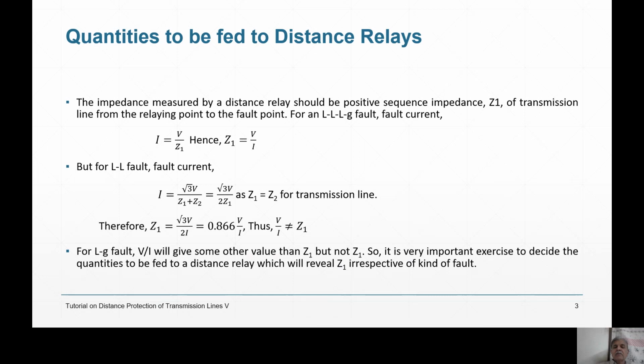If you go to a hilly area, the soil resistivity will be high. It is measured, and it is said that the earth resistance ZF can be as bad as, or as good as, 20 ohms to even 50 ohms. And that is multiplied by 3 in the formula, right?